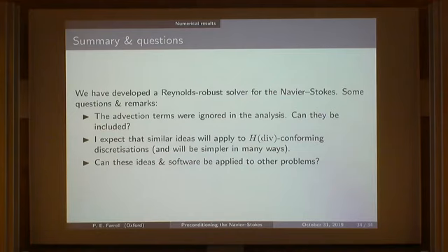And then for the stabilization for the beta, that was done purely by experimentation. So we solved up to Reynolds number 10,000 with a bunch of different betas, and then looked at the pictures and said, oh, which ones are oscillatory and which ones aren't. So there's sort of an eyeball norm going on there. Maybe that could be improved.